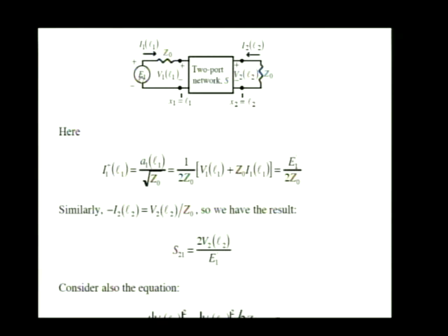Okay, what that's saying is I could calculate S21 with a paper and pencil calculation on a circuit if the two-port was some sort of a simple circuit by doing the following things. Connect up a Thevenin equivalent source with magnitude of E1 and Thevenin equivalent impedance Z0. Connect up a load of Z0 to port 2 and find the voltage V2.